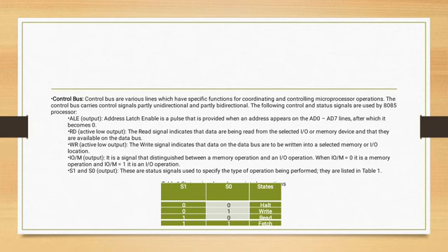So here you can see in this particular table, there are two kinds of status signals available in Intel 8085 processor. One is S1, another one is S0, and their operations could be written over there. So if we apply 00, that means both status signals are in reset condition. In that case, the processor is in hold state. When it will be 01, it will be in write state. When it will be 10, the processor will be able to read, and when it will be 11, then this is called fetch condition, or the operation will be a fetch operation. Okay.